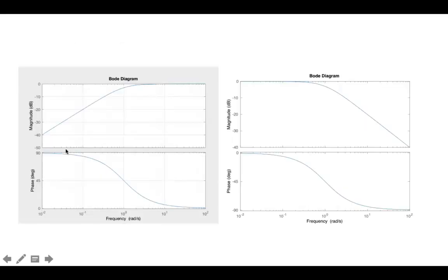So here was the magnitude versus frequency plot on a logarithmic scale for a high-pass filter, and here it is for a low-pass filter. Now let's think about what could happen if mathematically we multiplied these two graphs together. In the first place, a gain of 0 dB corresponds to a gain of 1 in a ratio scale.